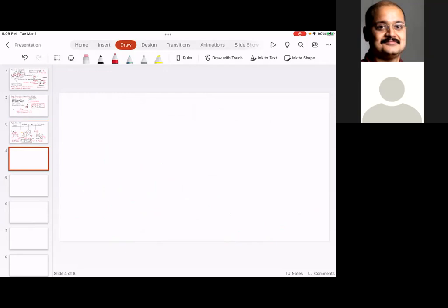On the left hand side, we have Wt. On the right hand side, what we have is sigma multiplied by B multiplied by Cp, circular pitch. What is the equation for circular pitch? Pi times m, multiplied by a factor y.